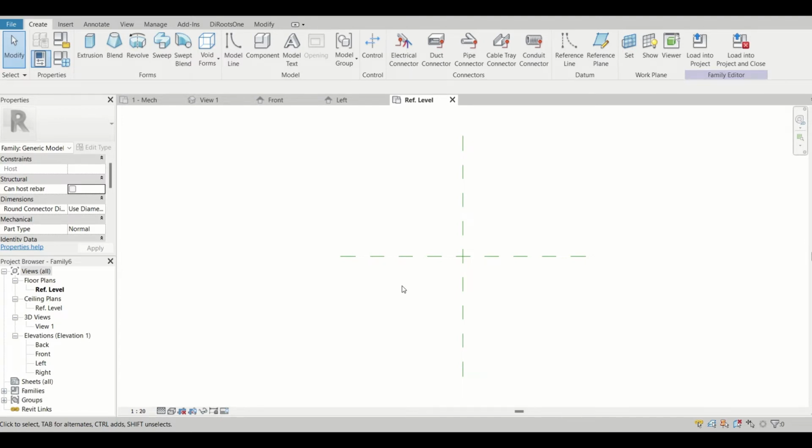For example, if I wanted to create any circular thing, for example a pipe, how can we make the pipe in this one? I'm not saying we are creating pipes, because pipes are default elements of Revit. But for example, the geometry like a pipe, whether it should be hollow or solid does not matter. So in this scenario, we'll go with both the solid and hollow portion.